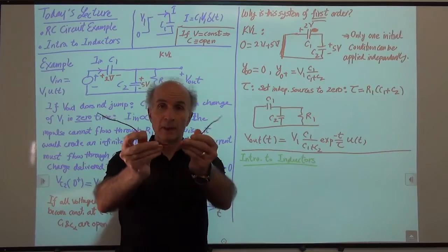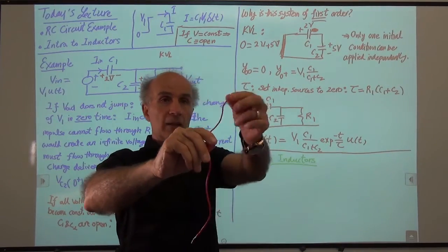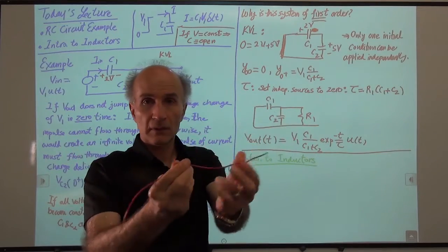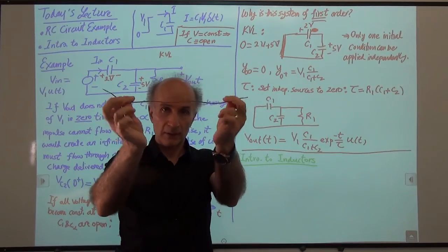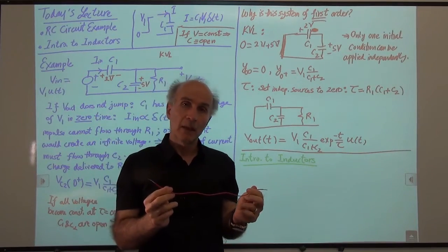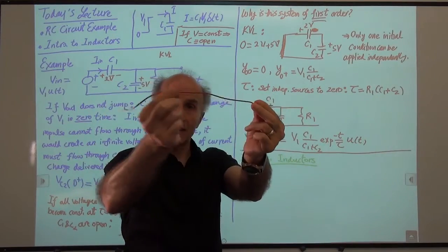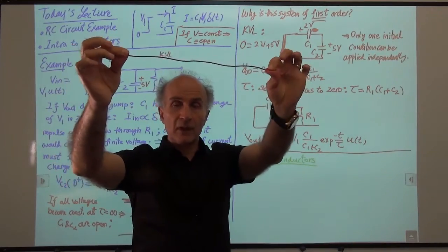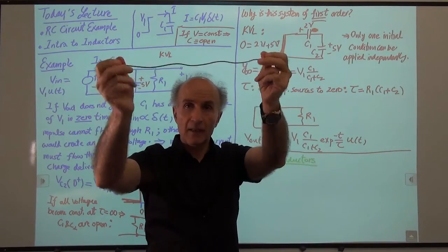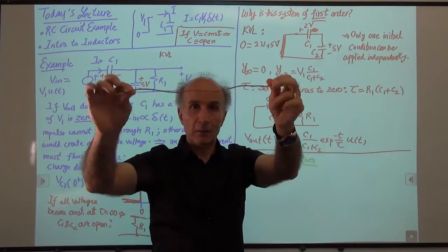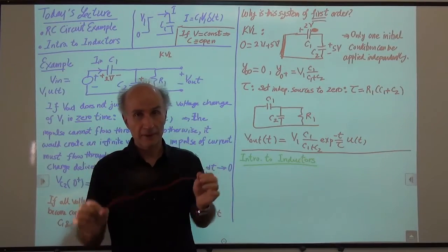So here's a piece of wire, right? As you can see, that's a piece of wire. It has these two ends. So this looks like a pretty good short circuit, right? You can try to connect 2 points of a circuit together. It's a short circuit. If you want to be more precise, you can say that this wire has some resistance associated with it, so it satisfies Ohm's law, right? So if you apply some voltage between these two ends, we're going to get a current, and that current is given by the voltage divided by the resistance. All right, so that's nothing surprising.